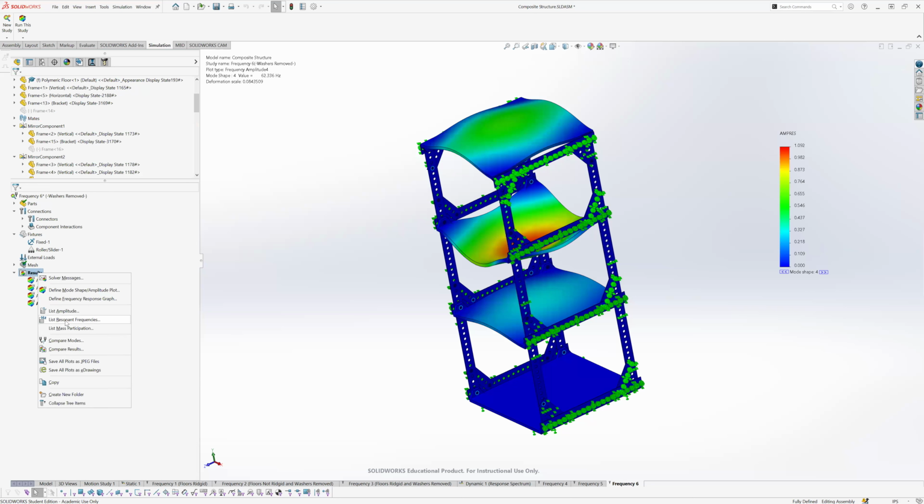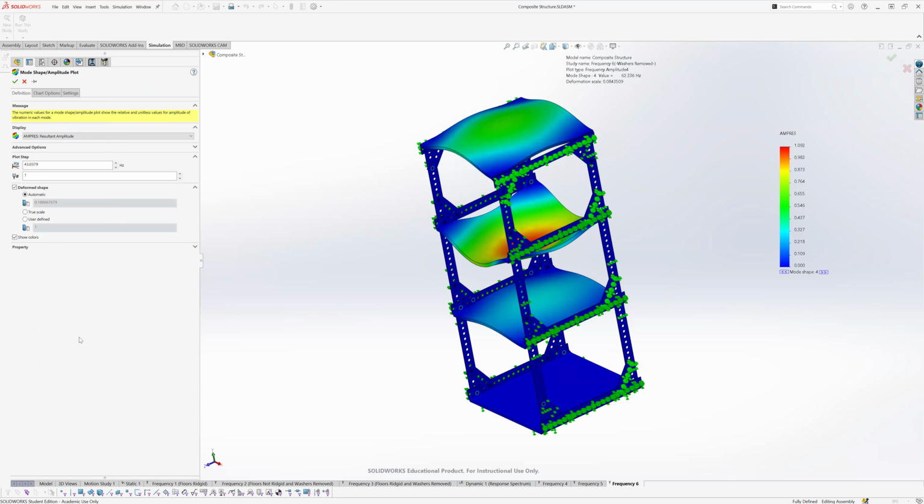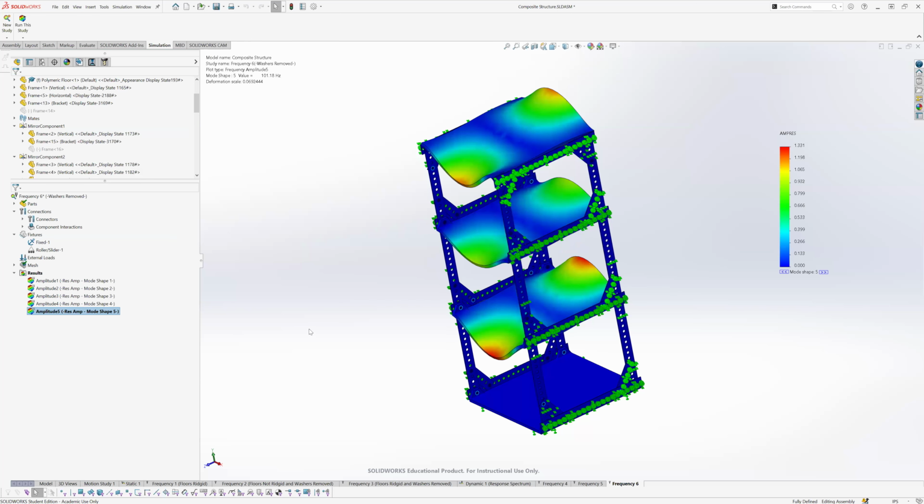Again, by default usually they have five, but since the first study only produced two plots, and then we copied that study, that's why it's only producing two. You can actually go into your settings and simulation and adjust this if you want more plots, so you don't have to do this. But if it's seven plots, it's not a big deal. Typically, if you have a certain frequency range, you're not going to need a tremendous amount of plots. So there's five, two more to go.